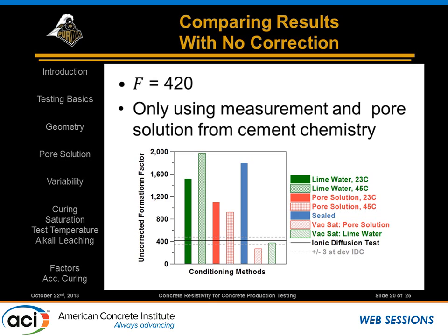Now, if we wanted to, you could put it in a bucket with near pore solution, but for some mixtures, this becomes a tricky endeavor because which pore solution do you use? Do you use a 1-day pore solution, a 5-day pore solution, a 90-day pore solution? All of those are better than sticking it in water, but it becomes a bigger logistical issue, we think, when you start to go to the field. We had questions on even calcium hydroxide, how much do you put in from people who are doing this in the field? And I think trying to come up with an alkali balance is going to be trickier.